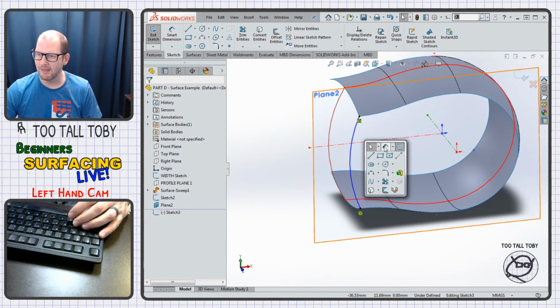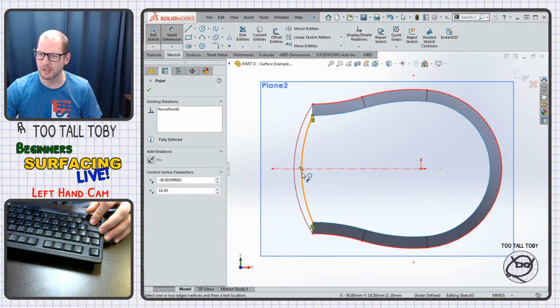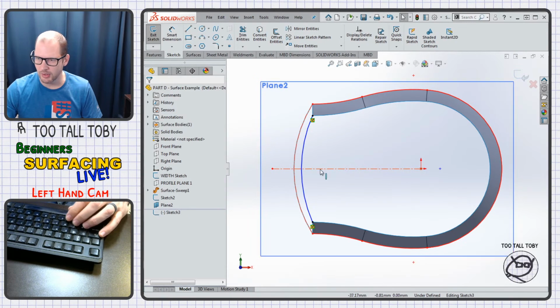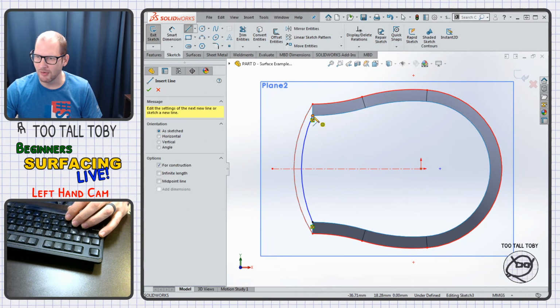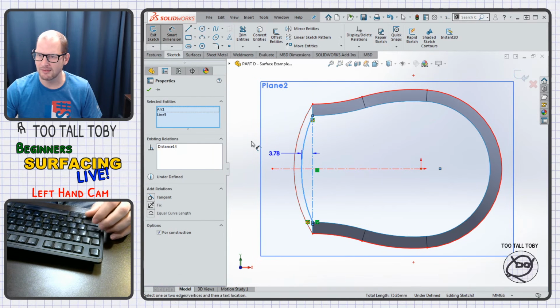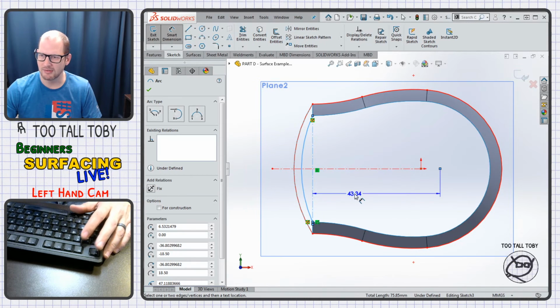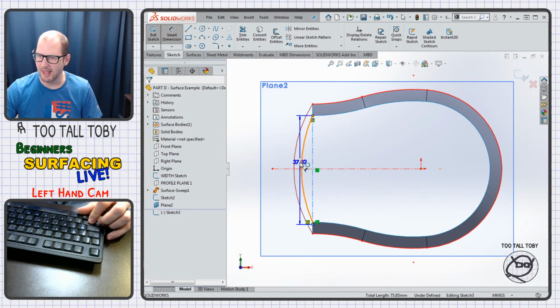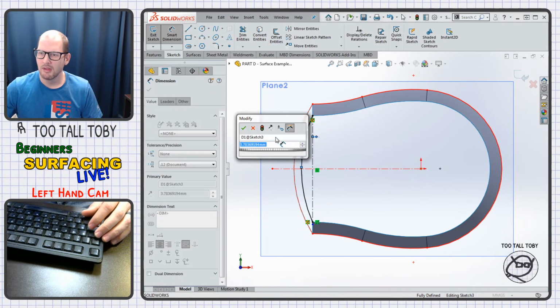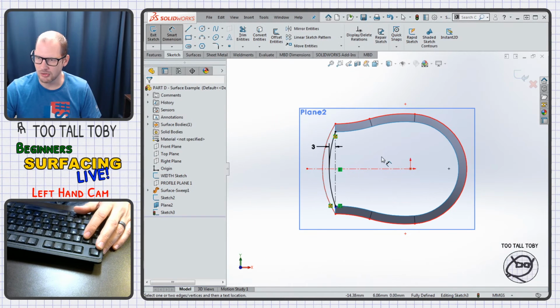So, and then finally, I'm going to create a dimension here. Now, this is a video that I did create, I think just a couple weeks ago, where you can create a dimension that goes maybe from this point to this arc here. And if you hold shift, you'll get a shortcut to the peak of that arc. But sometimes you have to have a line to do it. So it's just worth noting here that I've been in spots like this before where it's better with a line. Hold shift, and now you see I get the peak of that arc instead of getting the center point. Default behavior would be dimension to the center point, but if I hold shift when I do that, then I can get the peak of that arc for that dimension. So I'll make that 3 millimeters so that it's got a little bit more curvature there on the front, a little bit of weird curvature.